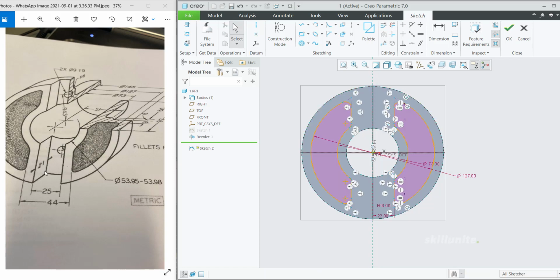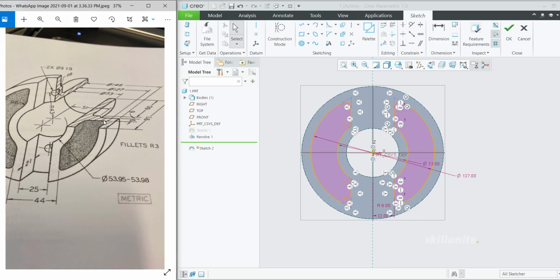So as you can see, both of them are having different depths. So you can see this thickness has to come like 6 mm. So we need to keep that material, so we need to consider that, and according to that we need to remove the material. So total is 60 plus 6 plus 6, so 72. So from 97 we need to leave 72.